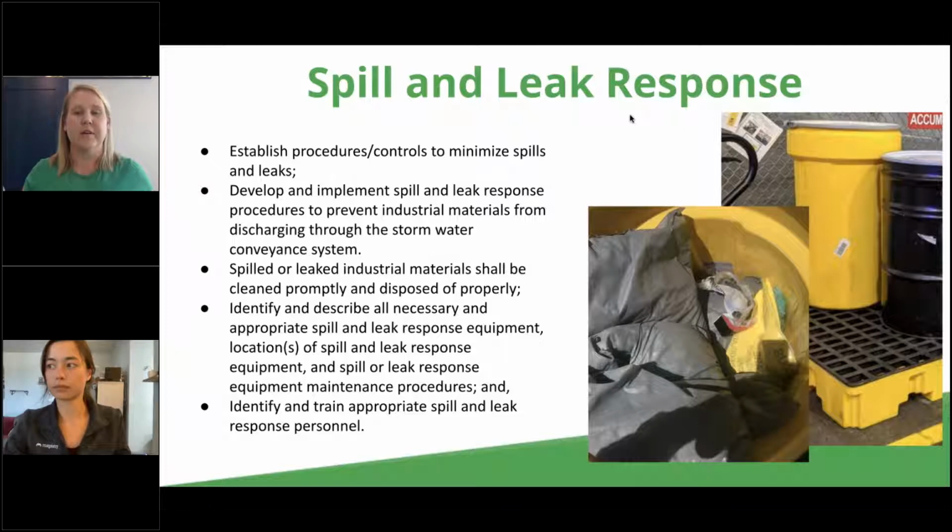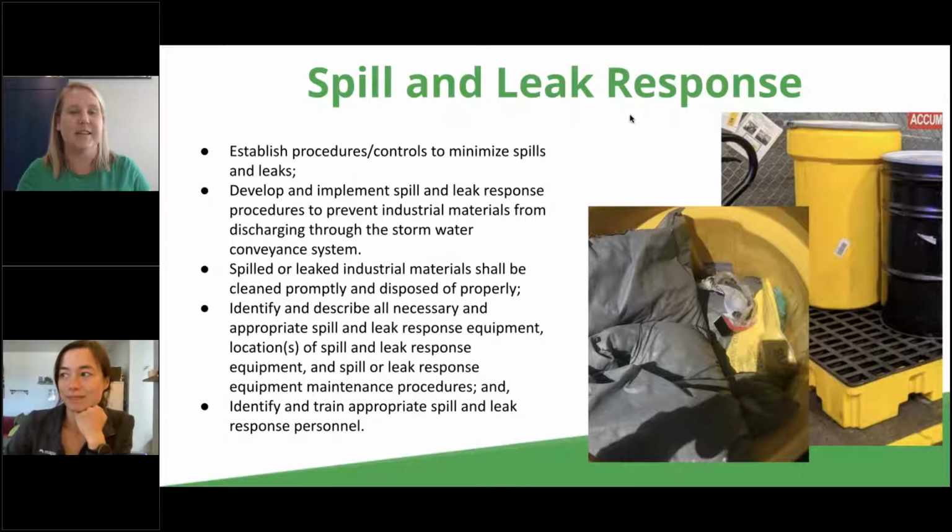You want to make sure that you always have materials in place to respond to those spills. This includes regularly checking your spill kits to make sure somebody didn't turn it into a trash can, and make sure the spill kit is still intact. And you want to make sure you have the right types of materials for the types of spills you expect to see. So you want to make sure you are staying on top of that spill and leak response program at your facility.